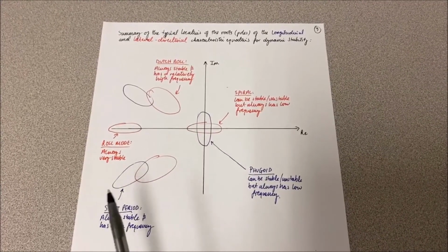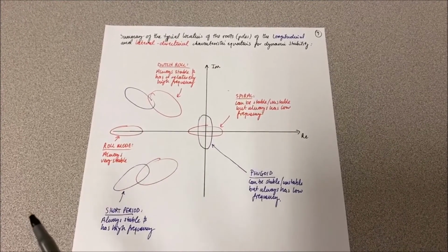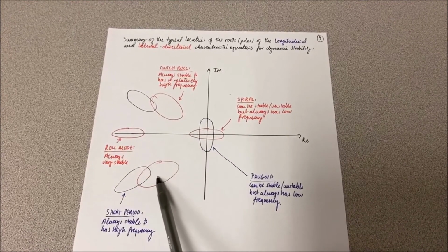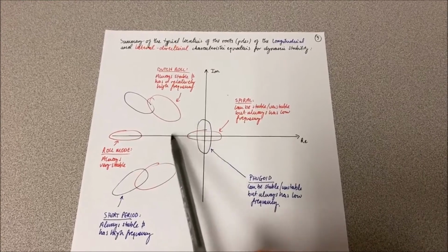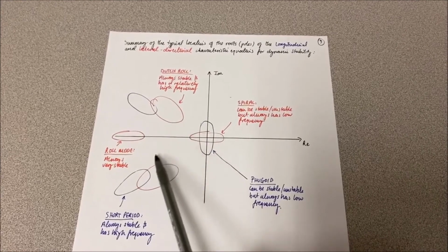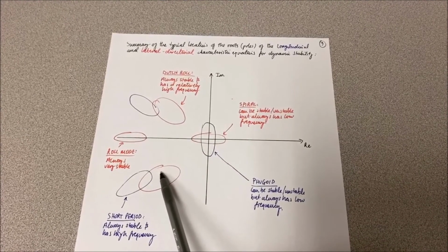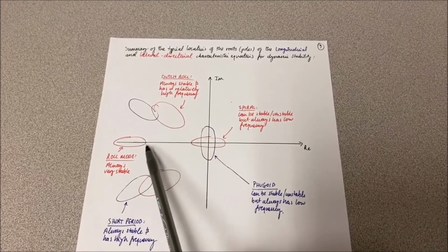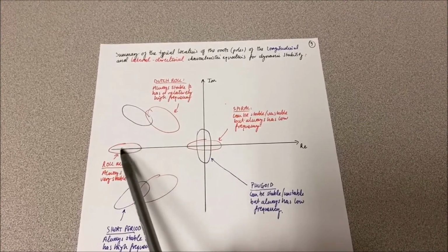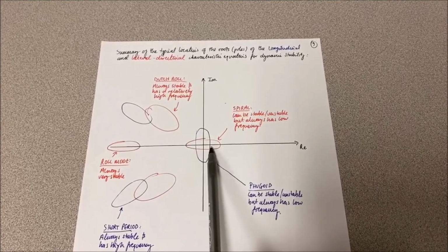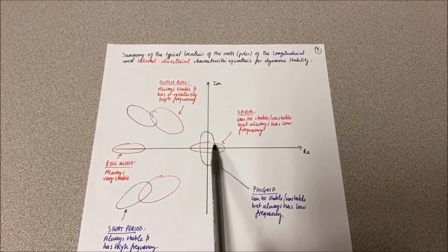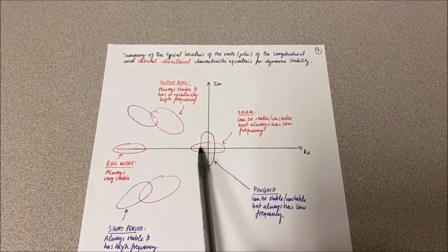And then we looked at the solutions to the lateral directional characteristic equation, and that gave us one complex conjugate pair, which was the Dutch roll. So a little bit less stable than the short period and has a little bit of a lower frequency than the short period, but is generally always stable. And then we had these two real roots, the most negative of which corresponds to the roll mode, which is always very stable and lives somewhere over here. And then the spiral mode, which we said could either be stable or unstable, but it also has a very low frequency and low damping, of course.